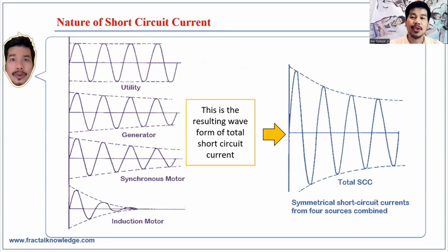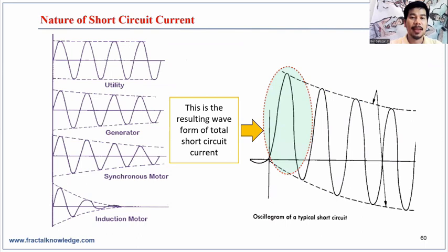It gives you the magnitude of the total fault current wave in the first 5 cycles traveling to the specific point in the electrical system to release the fault current. The graph shows symmetrical. Just like I said before, in an actual wave, asymmetrical is the shape. Imagine if those waves are asymmetrical. The first cycle fault, which is colored light blue, is very significant to study and consider in the design and sizing of the protection.